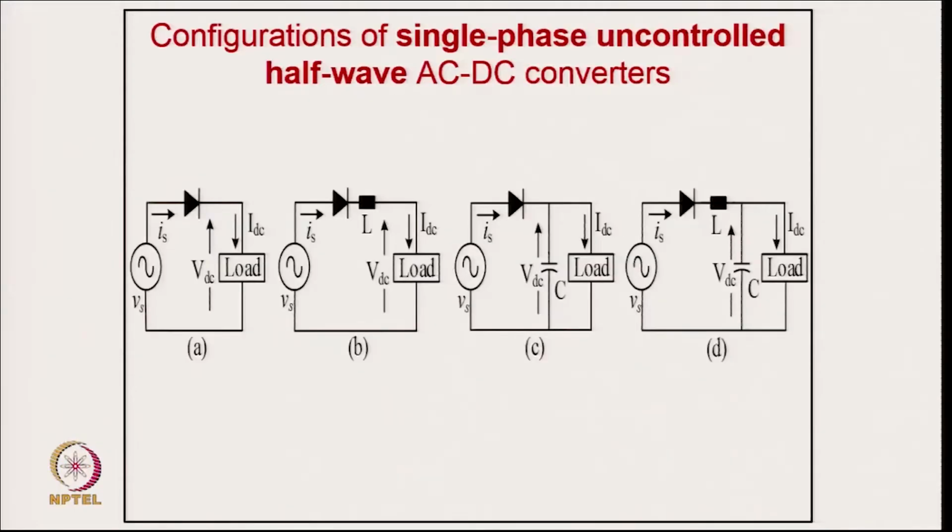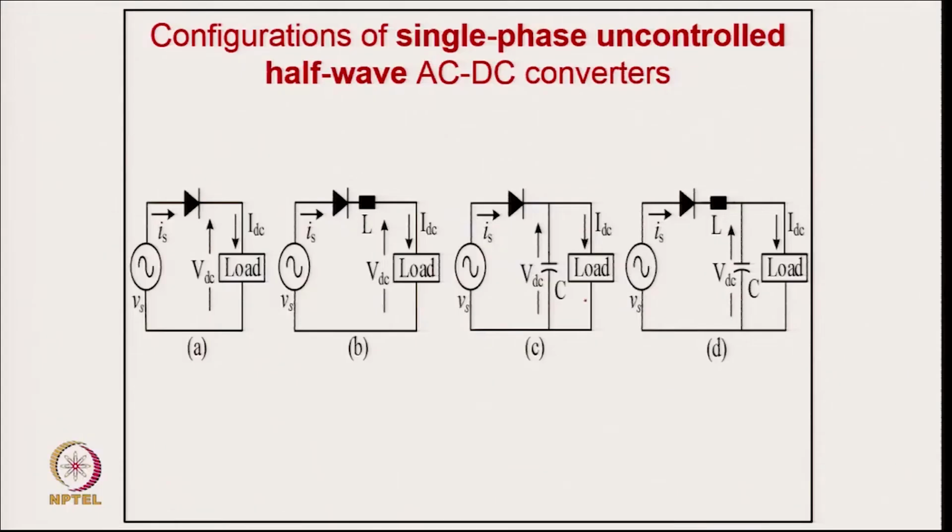So, first we would like to look at these, and then we would like to look into the improvement in these AC DC converters, so that power quality is inherently improved in these converters. Coming first to the single phase conventional AC DC converter, the first category is the half wave. Half wave we use in very low power ratings, probably a few watts only, either first with a simple load, then maybe an inductive filter, then a capacitive filter to drive a voltage source, or an LC filter. These are the typical configurations used in different applications depending upon the power rating. Half wave is also used extensively, not only connected with the grid, but typically in the final stage of switch mode power converters. We will discuss that also.